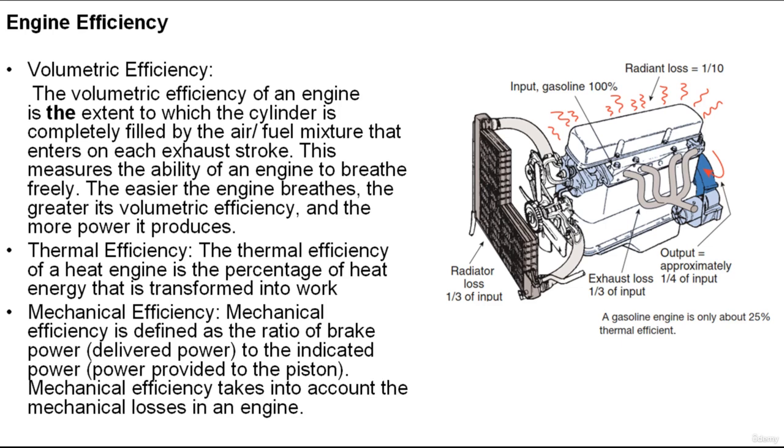Typically, engines have a volumetric efficiency of 80 to 100% if they are not equipped with a turbo or supercharger. Basically, an engine becomes more efficient as its volumetric efficiency is increased. Also, we have the mechanical efficiency. Mechanical efficiency is a measure of how much power is available once it leaves the engine compared to the amount of power that was exerted on the pistons during the power stroke. Power losses occur because of the friction generated by the moving parts. Minimizing friction increases mechanical efficiency.